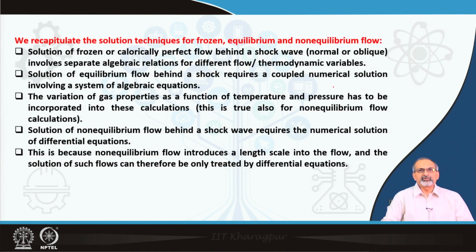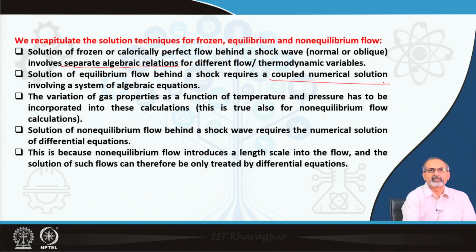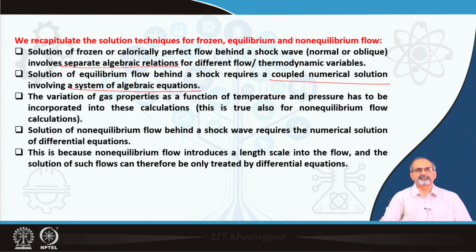This is a brief recapitulation of the solution techniques for frozen, equilibrium and non-equilibrium flow. Solution of frozen or calorically perfect flow behind a shock wave, which could be normal or oblique, involves separate algebraic relations for different flow and thermodynamic variables. Solution of equilibrium flow behind a shock requires coupled numerical solution involving a system of algebraic equations.